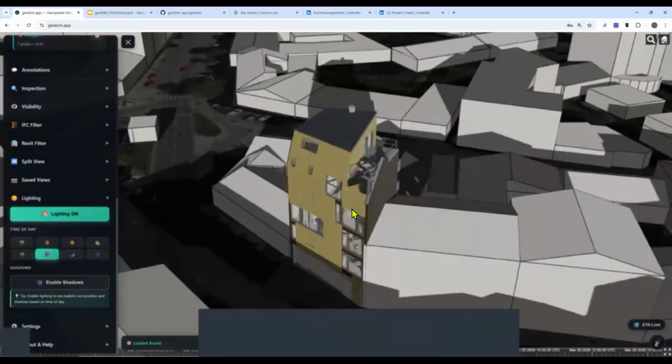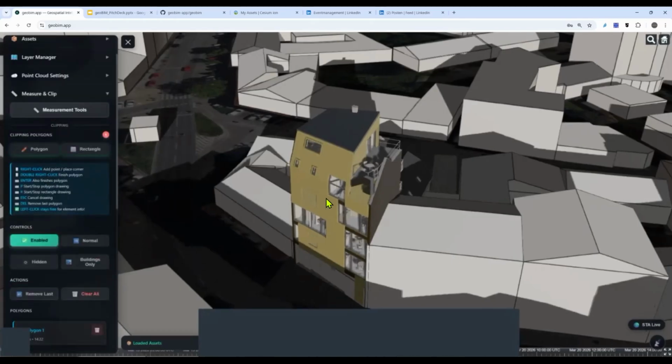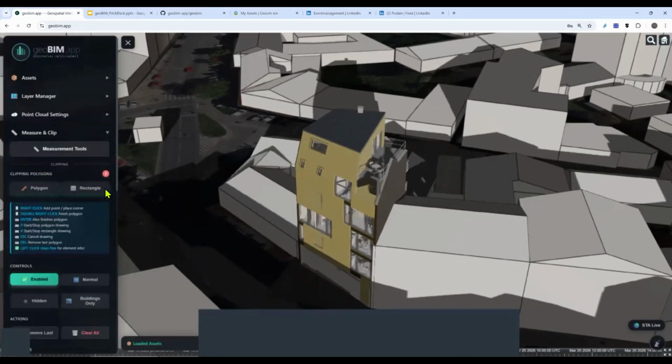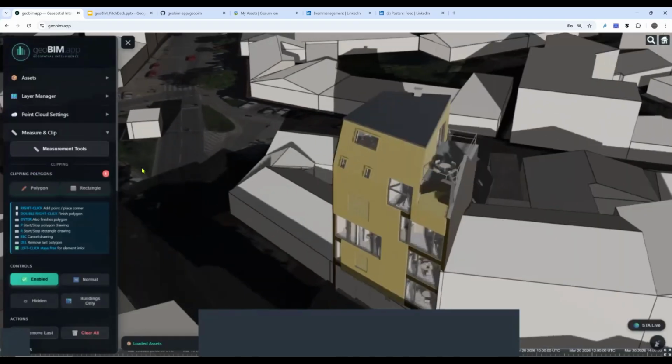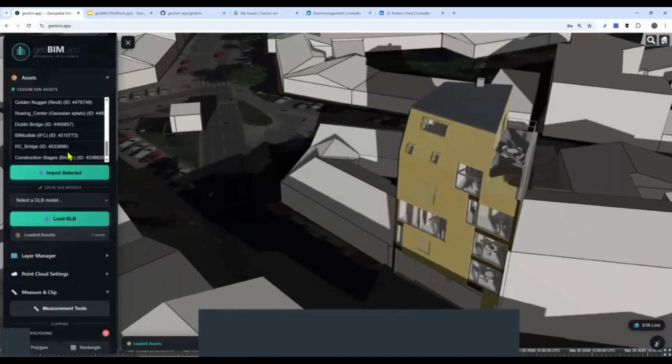Right, so that was for building design. How about other assets that are coming maybe from photogrammetry, reality data? And think about it, I always leave those assets here in these scenes. I don't delete anything or change projects. It's all one session in which I load different assets. So let's go to a bridge that was coming from photogrammetric reconstruction. So that means you take a drone, you do hundreds of pictures that are overlapping, and then CesiumIFC will convert those into reality meshes or point clouds or Gaussian splats.